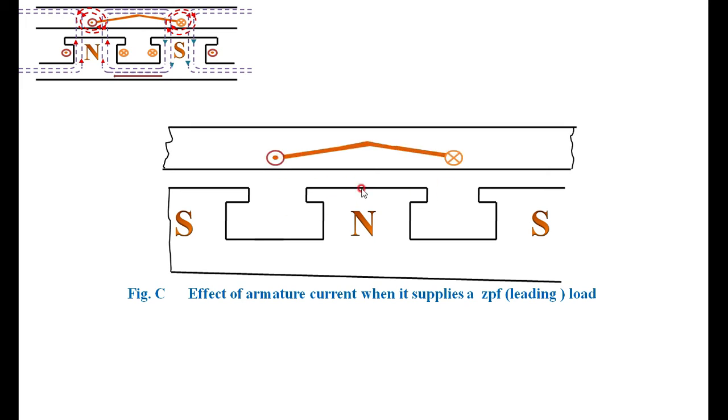I am shifting. This is the original position for a unity power factor. Unity power factor. Both current and voltage are in phase. Now to make current to be lead, then you have to shift this to 90 degree in the left side. Therefore, it becomes leading. That is, the current is leading the voltage by an angle of 90 degree.